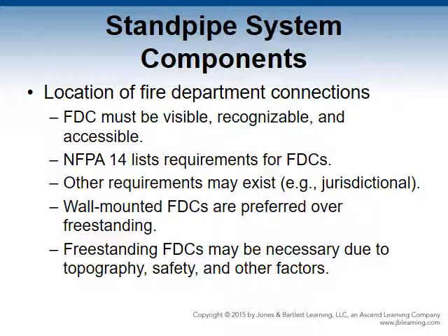Wall-mounted FDCs are preferred over freestanding FDCs. They have less exposure to the environment. Freestanding FDCs generally receive less maintenance. Freestanding FDCs may be necessary depending on the topography, required hydrant distance, and other safety concerns.